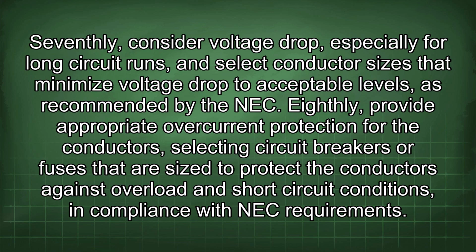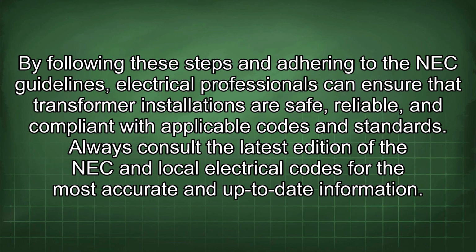Eighthly, provide appropriate overcurrent protection for the conductors, selecting circuit breakers or fuses that are sized to protect the conductors against overload and short circuit conditions in compliance with NEC requirements. By following these steps and adhering to the NEC guidelines, electrical professionals can ensure that transformer installations are safe, reliable, and compliant with applicable codes and standards. Always consult the latest edition of the NEC and local electrical codes for the most accurate and up-to-date information.